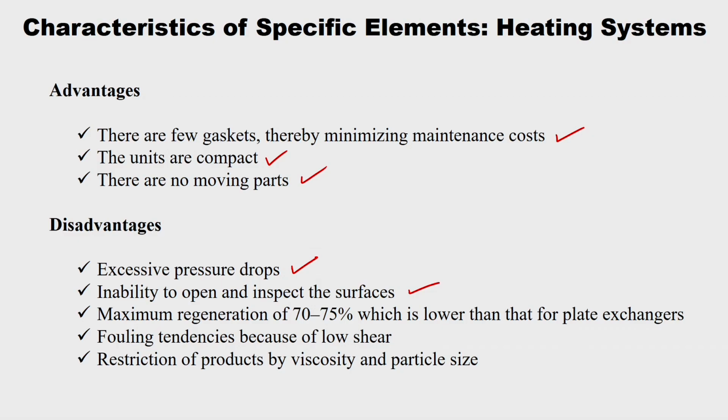In the plate type we have that flexibility that I can remove or add plates and it is easy to inspect, but here we lose that. And there is a maximum regeneration of 70 to 75%, which is lower than that of the plate heat exchangers.